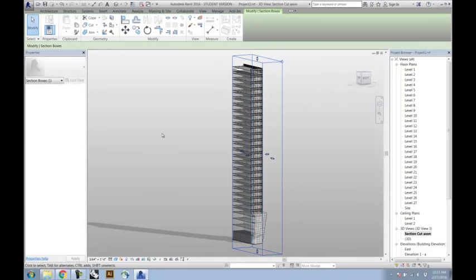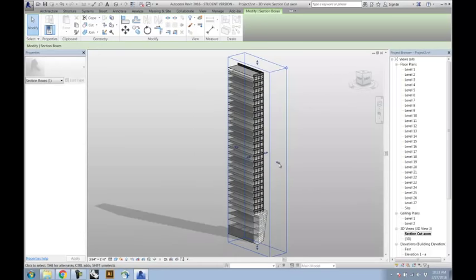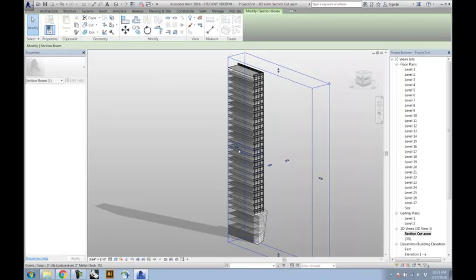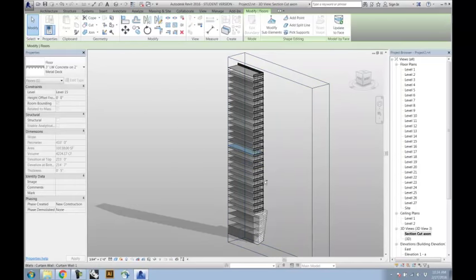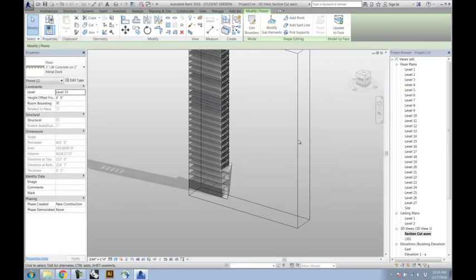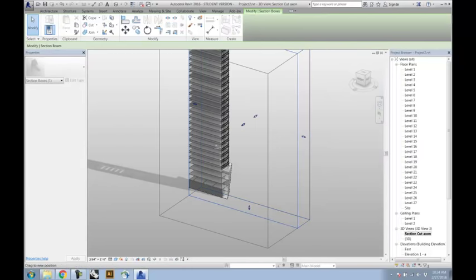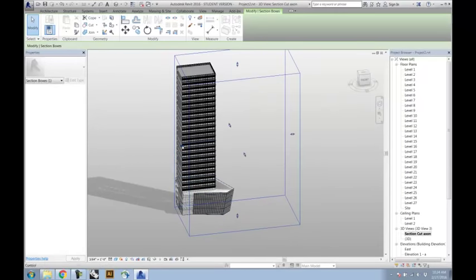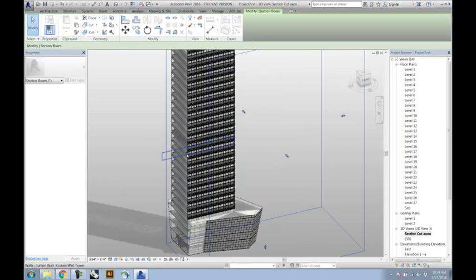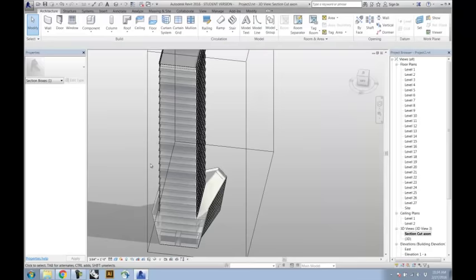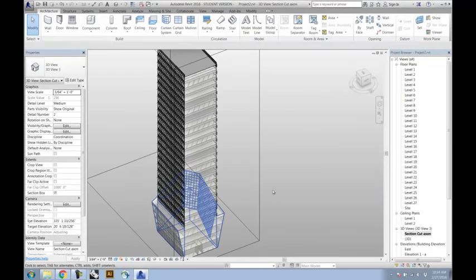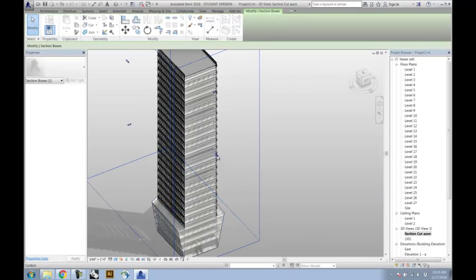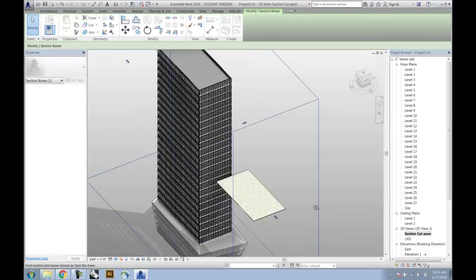You can see here in this view, I've actually got the section box turned on, and I'll show you how to do that in a second. These section boxes allow you to, if I select the section box, I can pull on these faces and it's actually cropping the tower geometry. Again, a good way to make some simple diagrams that start to explain the project a little bit better. Once you put this big curtain wall on, it tends to really slow down the file. So if I get that blue arrow highlighted, then I can pull on the section box.